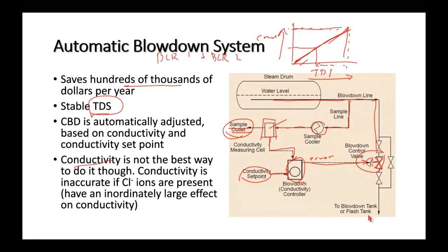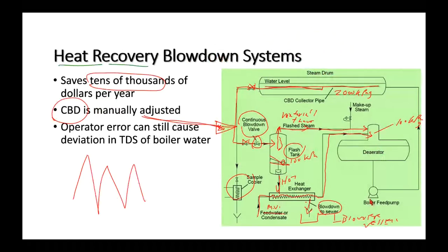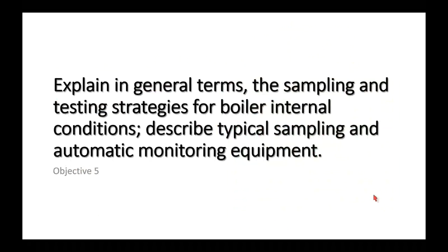And by the way, there's no reason we cannot be flashing that blowdown water and recovering the heat to the deaerator, and using a blowdown water heat exchanger as well to be transferring heat to the makeup water. So we can combine this with that. And there's our blowdown.